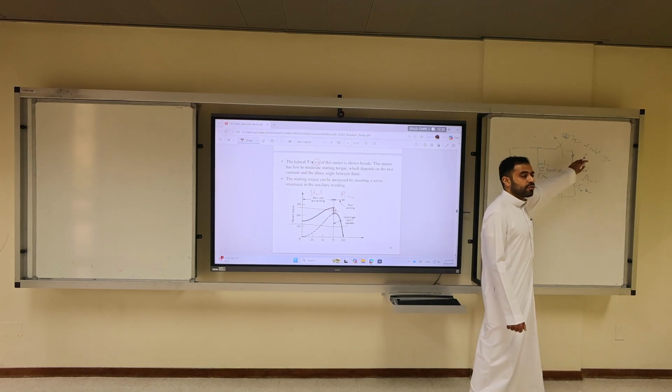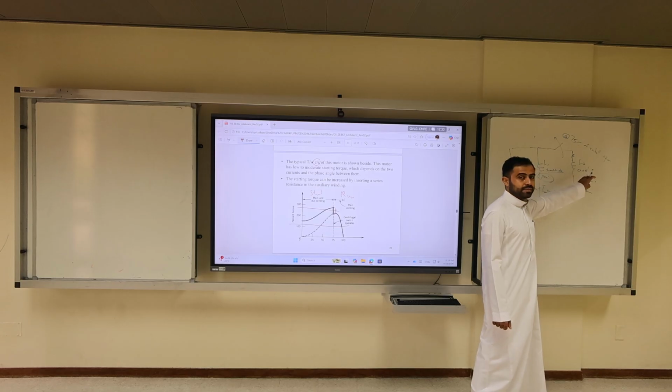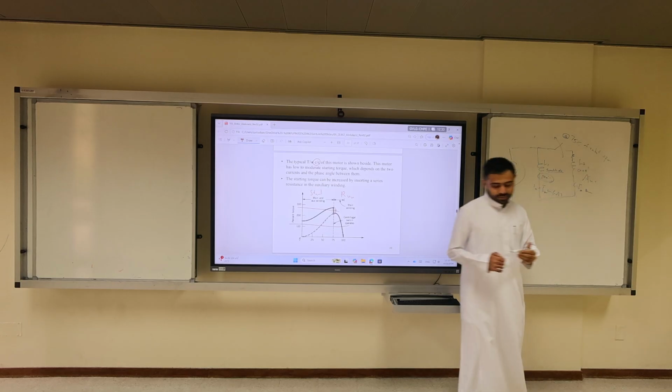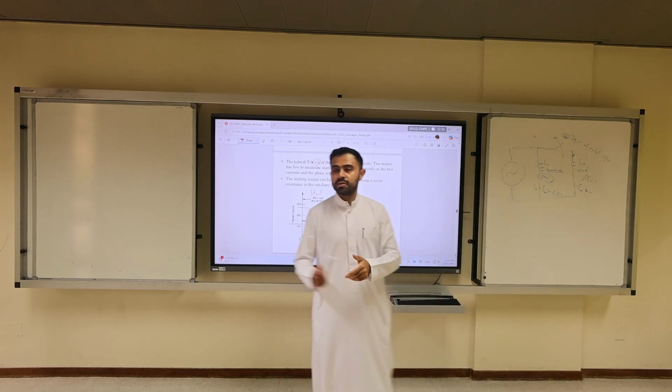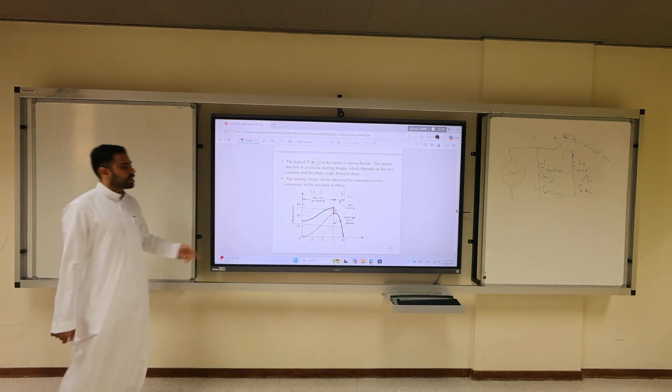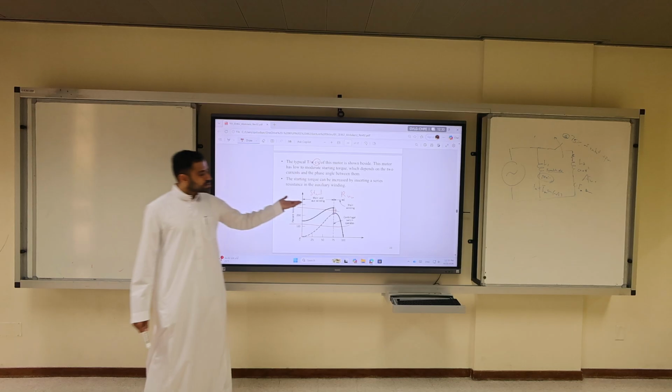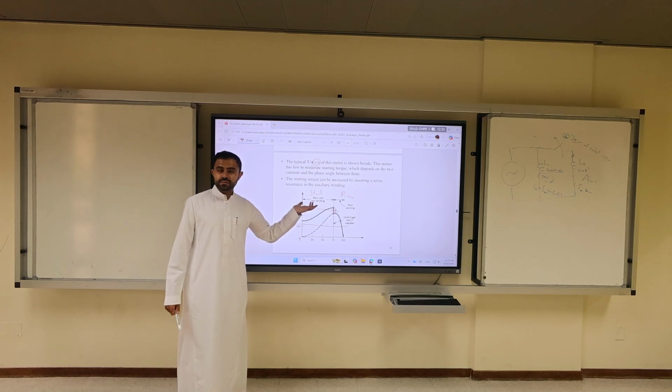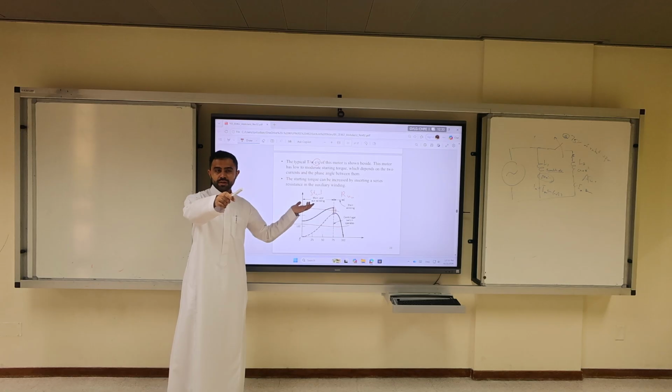You increase R over L without having a bigger L. That's one solution. But what is the cost? The cost is heat, losses, etc. And remember, which one has wider cables? Main or auxiliary? Main. Okay, this is very important.